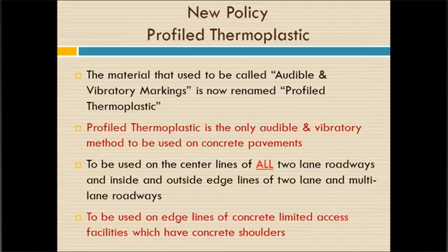But the other major change had to do with the grinding on limited access facilities on concrete. The pavement marking people did not want us to be grinding on concrete because of the effect to expansion joints. So if you look at 518, you'll notice that on concrete pavements with asphaltic shoulders, we've moved the rumble strip over onto the asphalt.